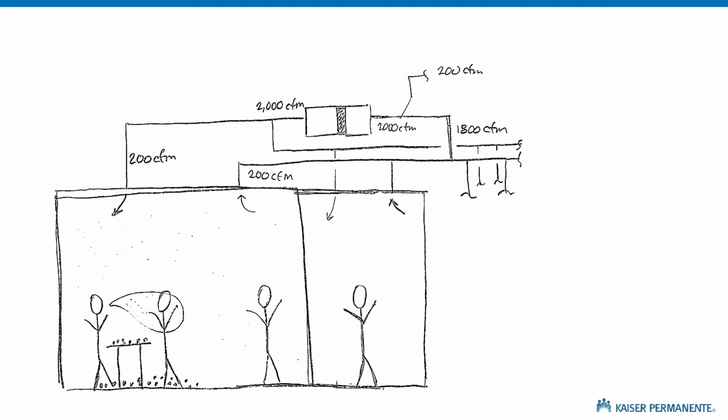The way that I've been doing this year is kind of a simplified method that I'm calling EBDF. I've said it so much that I have an acronym. So EBDF stands for the exhaled breath dilution factor, and here's how it would work. Stick figure on the left is a human producing 6 liters a minute of breath, which is 0.2 cubic feet per minute.